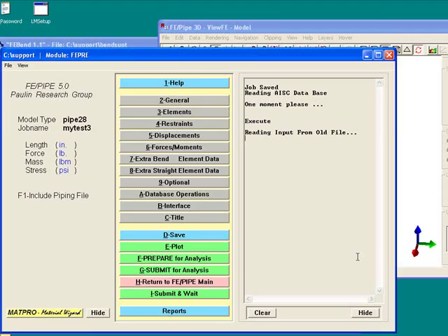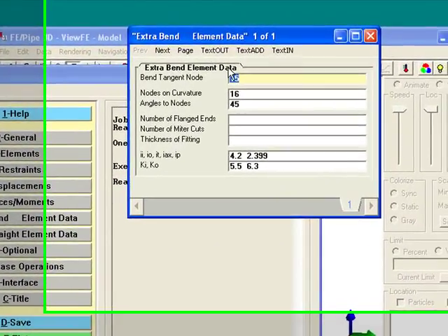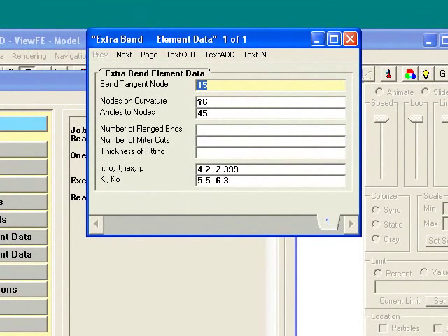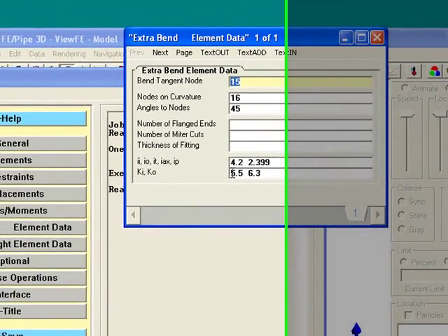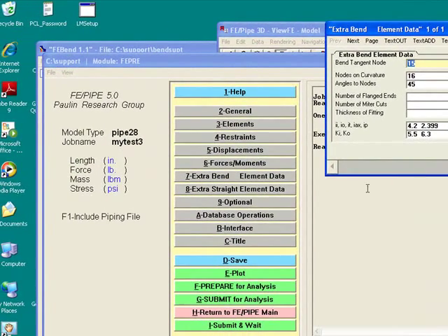So we go back to our beam model, and for the bend at node 15 at 0.16, which is going to be at 45 degrees along the bend, we're going to put in the calculated in-plane and out-of-plane stress intensification factors and the slightly reduced flexibility factors. So now we've got a better model for the bend with stanchion.